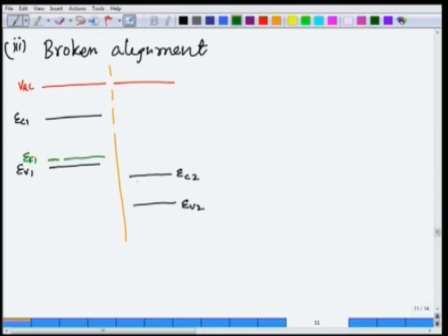Let us assume, just so that this Fermi energy is here, p type, this is EF1, and let us take this n type, this is EF2. Deliberately I am doing that, otherwise the alignment will be too much off the screen, and hence it will be difficult. And this is psi 1, and this is psi 2. This is the electron affinity of the second material. What happens if you join them again?